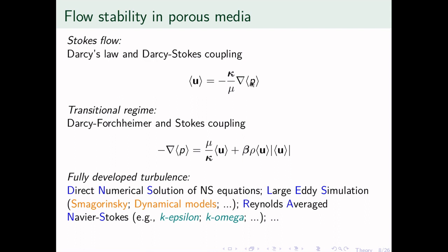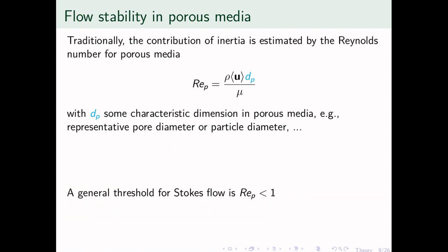those flow parameters to calculate permeability, and either permeability and the beta coefficient here, if we're talking about Darcy-Stokes only, the permeability, and if we're talking about Darcy-Forchheimer systems, the permeability, and also the non-Darcy or beta coefficient in this case. Beta is usually also called the Forchheimer coefficient.